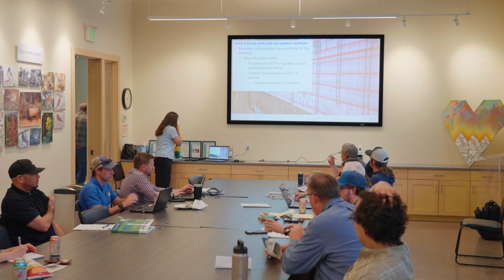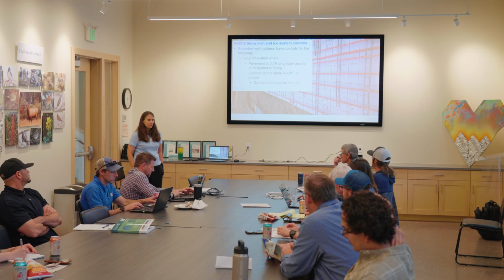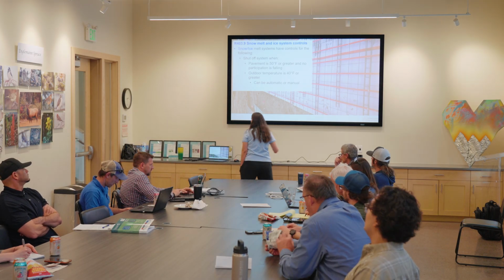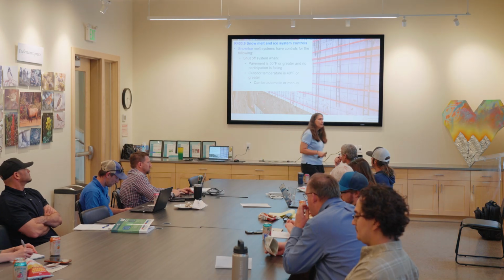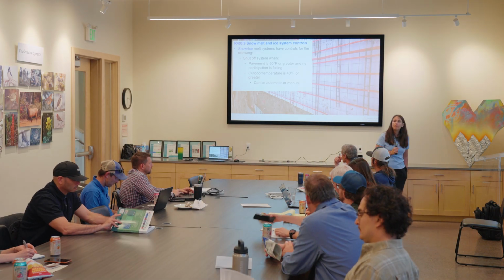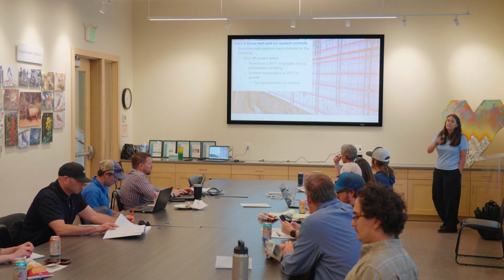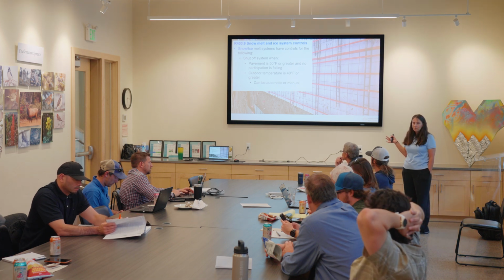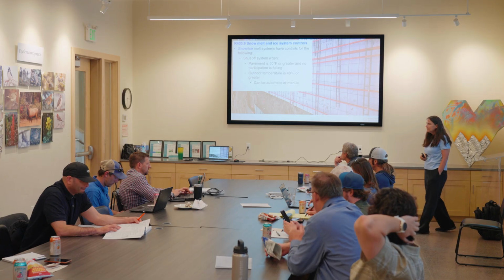So here's the fun thing. When we're talking about existing buildings, we actually don't start in Chapter 4. We start in Chapter 5. And Chapter 5 tells us what provisions out of Chapter 4 we have to comply with. Now, because it's a change of occupancy, you basically are treating it as if it was a brand new building. But I had to throw in the Chapter 5 conversation with it.